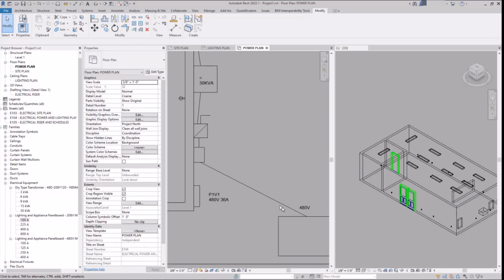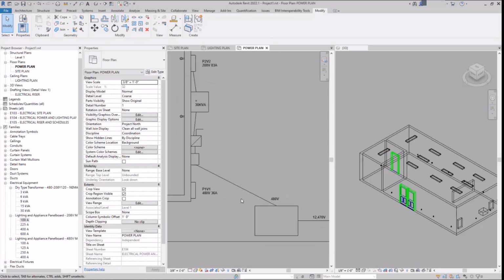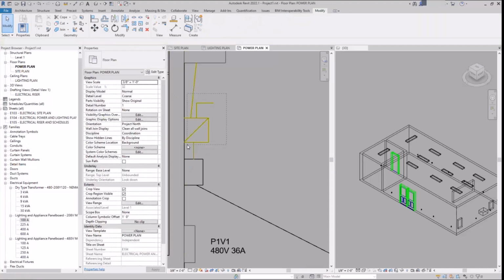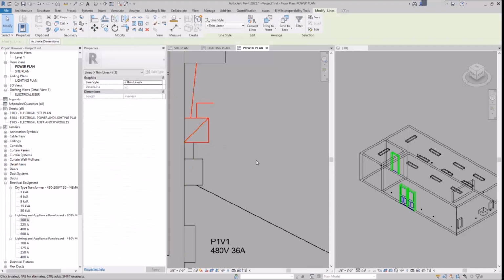Okay. So according to the NEC, the utility is going to own obviously the transformer, this line. The customer will own the meter typically, and from the secondary side of the meter, the load side of the meter, that's when the customer's wire comes into play. So this is the load side of the meter. So customer, all this is customer stuff. Gotcha. Okay, I think so.